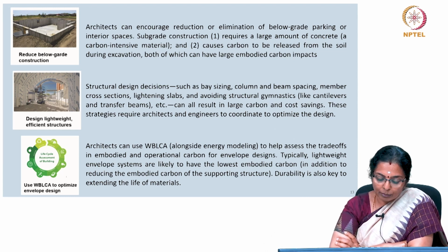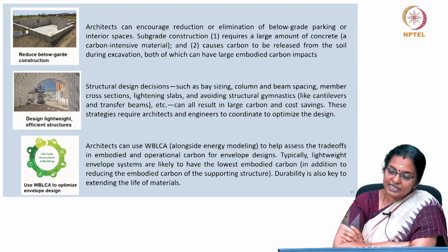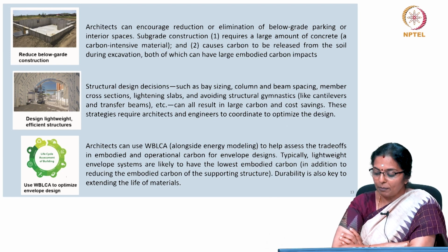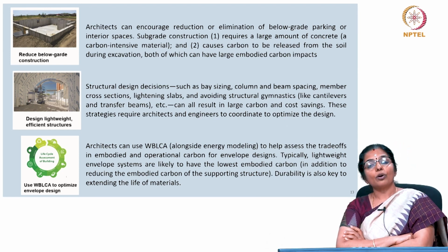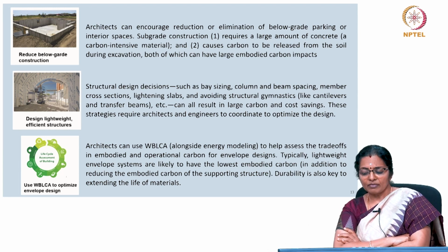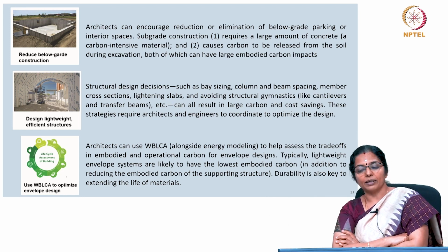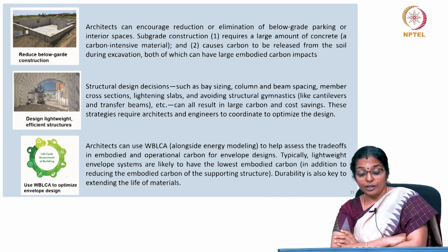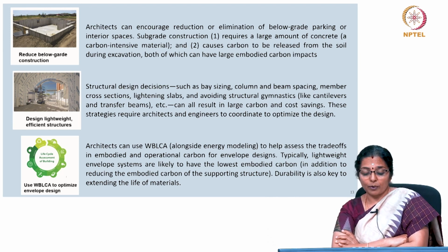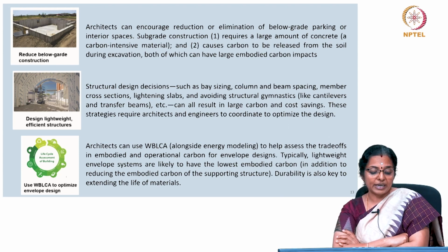Architects can use WBLCA alongside energy modeling to help assess the trade-offs in embodied and operational carbon for envelope design. Typically, lightweight envelope systems are likely to have the lowest embodied carbon, in addition to reducing the embodied carbon of the supporting structure. Durability is also extremely important to extending the life of materials.